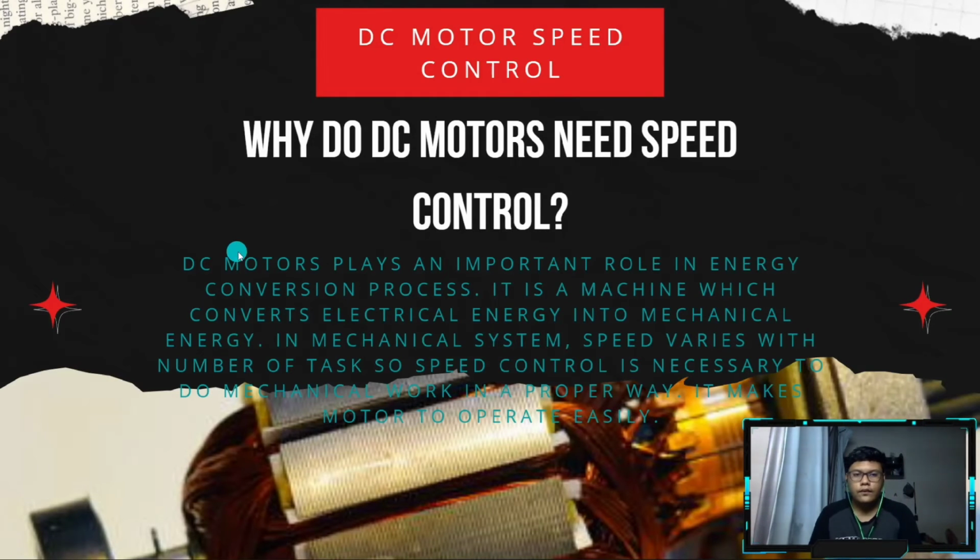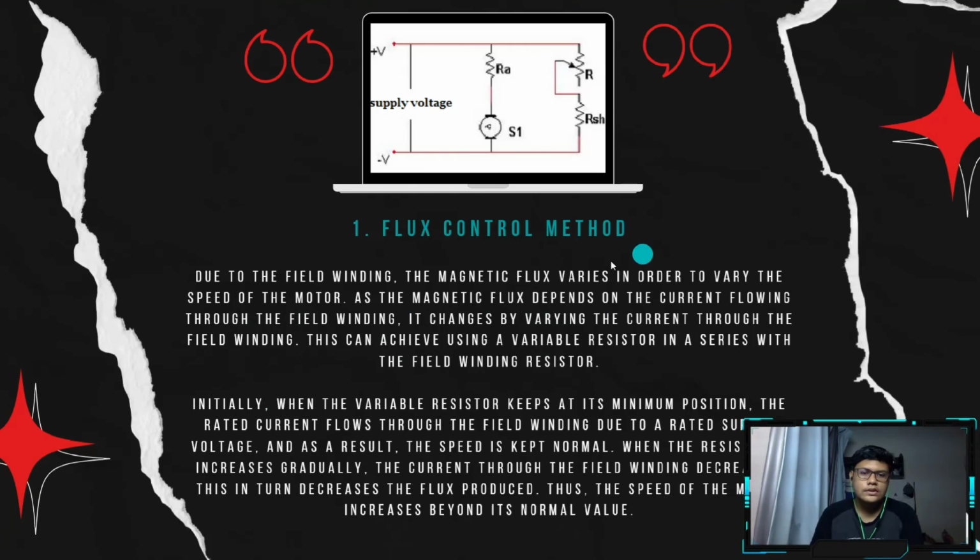There are 3 types of motor speed control. First is the flux control method. Due to the field winding, the magnetic flux varies in order to vary the speed of the motor, as the magnetic flux depends on the current flowing through the field winding. It changes by varying the current through the field winding. This can be achieved using a variable resistor in series with the field winding resistor.